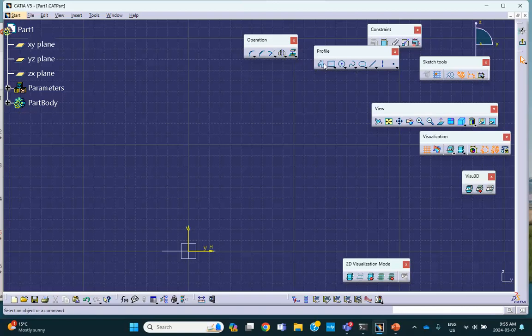On the profile, I'm going to start here at the center, go up, and instead of making a fillet, what I do is create a circle here, left click down, slightly move, okay? You do it any way you want. You have to create something like that. Let's dimension these things.